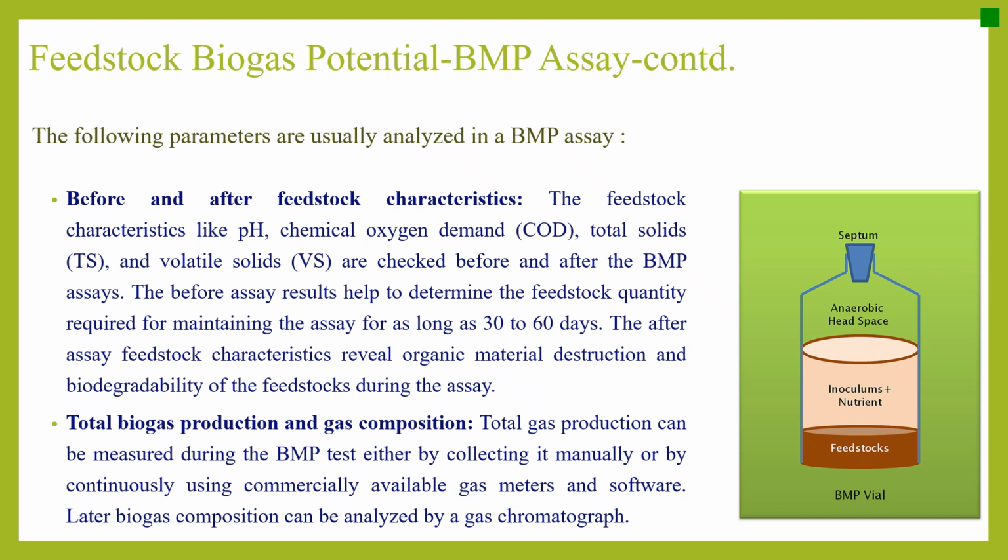and also the total biogas production and gas composition. Total gas production can be measured during the BMP test either by collecting it manually or by continuously using commercially available gas meters and software. Later, biogas composition can be analyzed by a gas chromatograph.